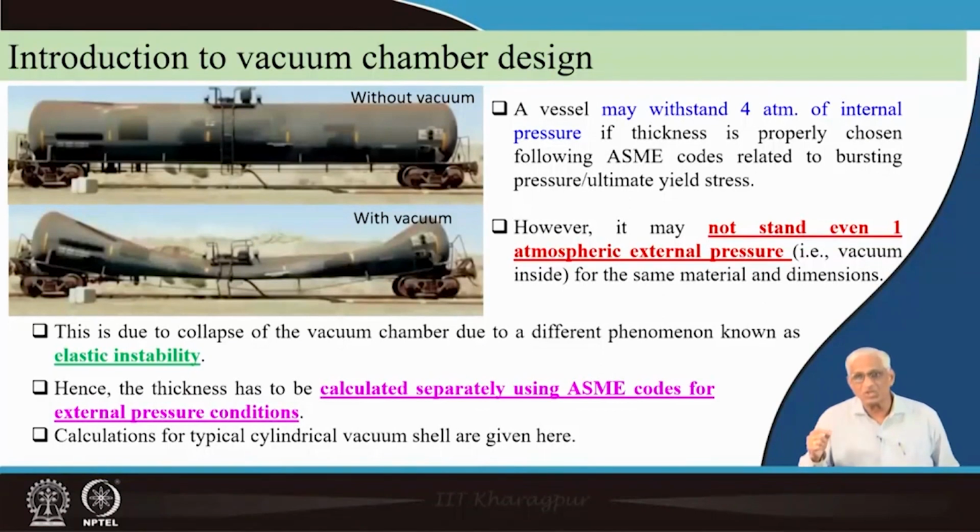For such issues, if a chamber is tested up to 1 millibar, you don't have to test it up to 10 power minus 10 millibar because of a simple relationship. 1000 millibar, that is 1 atmosphere absolute, minus 1 millibar is the same as 1000 millibar minus 10 power minus 10 millibar of a UHV unit. So, with respect to mechanical force, implosion or thickness calculation, it is good enough if you test the chamber up to 1 millibar.